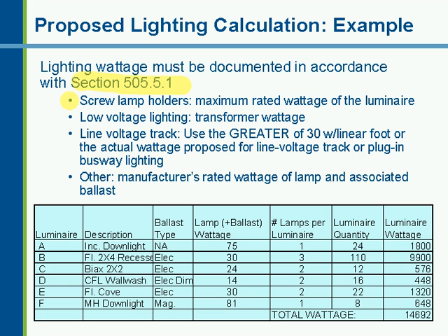And if you're putting in a lower wattage, that might be a problem showing compliance. If you can find a fixture that somehow can be labeled with the wattage you're going to put in it, that would be much better for your compliance. For low voltage lighting, it will be the transformer value for that low voltage system that you have to include